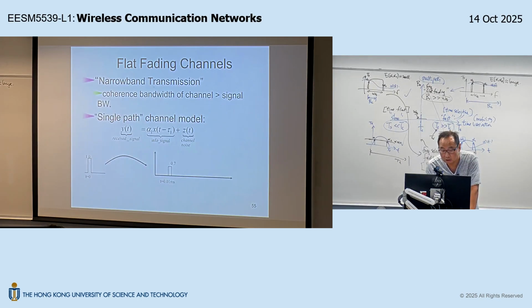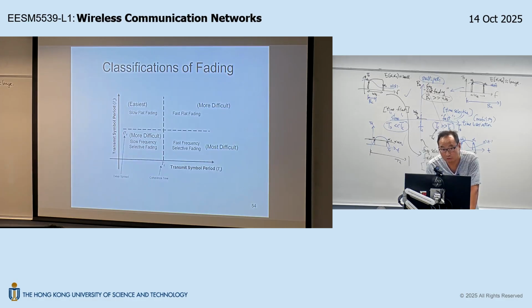Okay, so let's drill into the first case. Now, without loss of generality, we will always assume the time mobility psi is slow fading. Okay, so without even mentioning slow all the time, we just drop the adjective, assuming that it is slow. Okay, and slow means when you transmit the modulation symbol, the entire modulation symbol will experience uniform fading. Okay, that is what we mean by slow. So that means you don't have too much distortion on your transmitted symbol. Okay, that is to say.